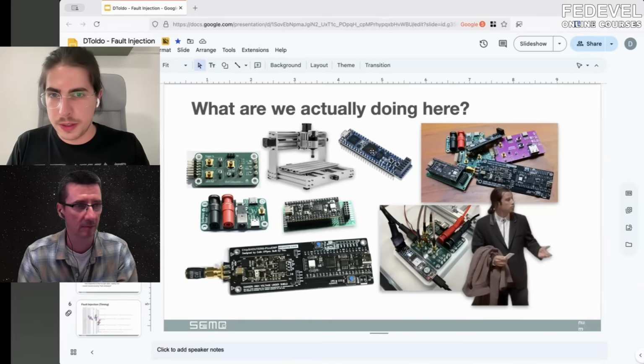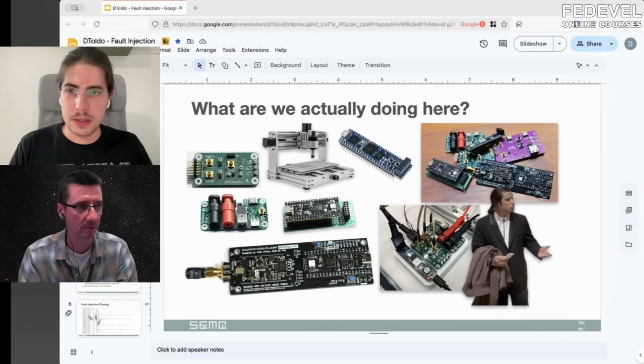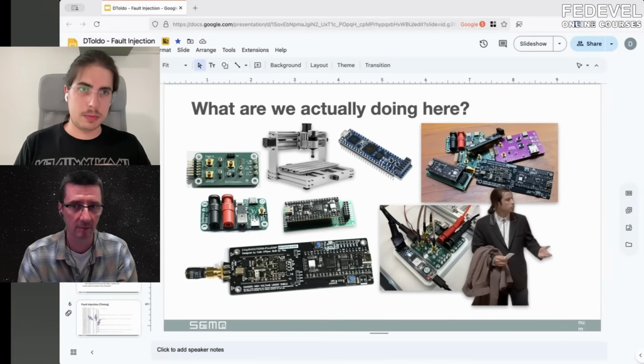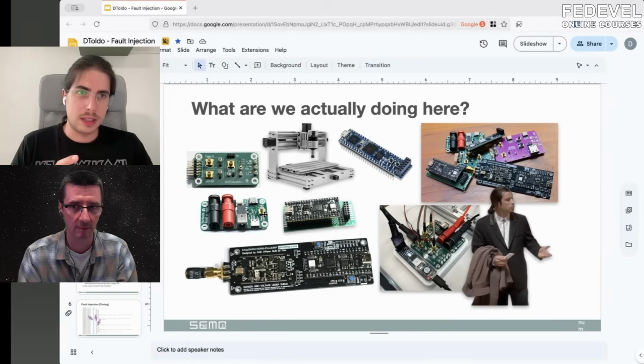Then we have FPGA on the right of it. We have a Raspberry Pi Pico below it. We have a power supply connector board that you can see, which I made for resetting the target. Sometimes they reset through fault injection, but in a weird state. So some registers still have values and it's stuck in some sort of weird boot loop. So I need to programmatically be able to reset it in a clean state. So this is just convenient connectors, a MOSFET, and then I can use a GPIO to power cycle it completely if needed.